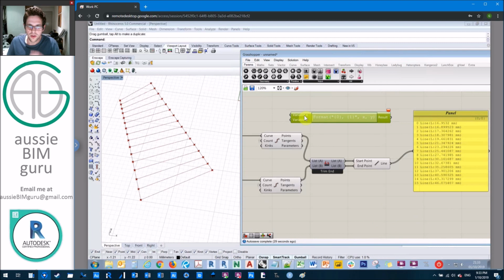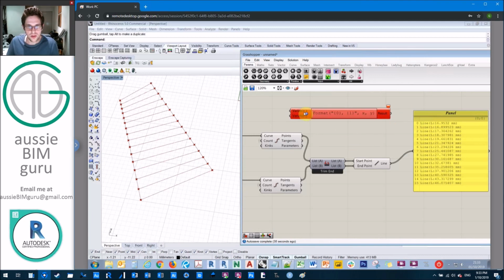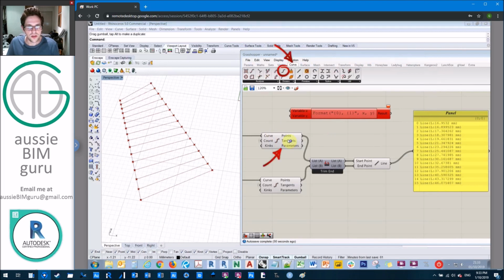And let's say I want to know where this came from in my palette. So I believe that to find something in a palette, you hold down Control and Alt and click and hold, and you can see it tells you where it came from. It tells me it's from maths and it's under script. Likewise, I could hold down Control Alt, go to curve, and you'll see it's telling me it's under divisions in curve for divide curve. So really easy to find components if you weren't sure where they initially come from.